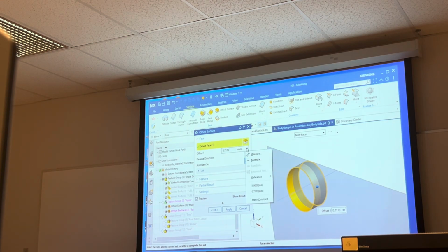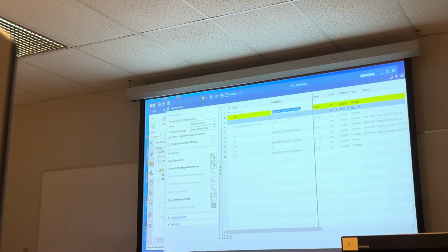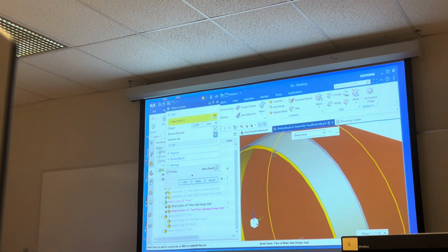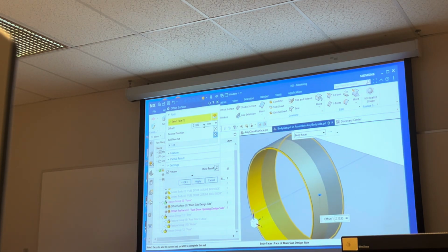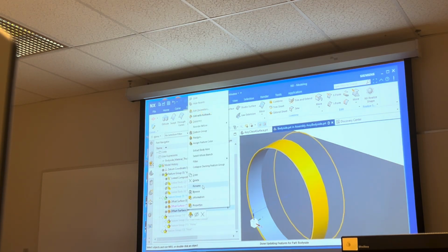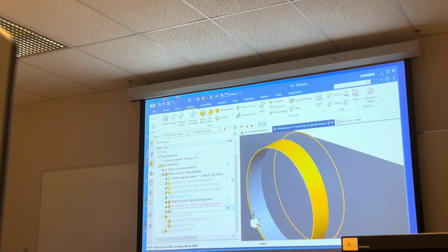So I'm gonna go to equals, go to formula, and it's already got the material thickness, but how do you do 3 times? You can do an asterisk and a 3. I hit enter and it's 2.133, it's still not much, it's still 2 mils, but it's coming out a little more than 2 mils, okay? But we're gonna name that. And again, the nice thing is we don't have to worry about the sheet by name. So that is gonna be door opening.